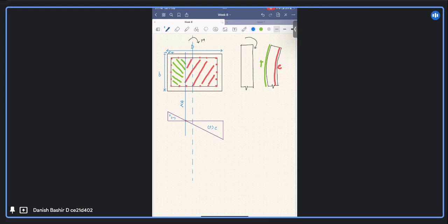So now we have to find the strain at each reinforcement, and then we have to find the total compressive force acting on it, and the total moment coming on it. For that, the code gives the formula like this. This can be easily derived from integration, but we will not go into the detailed calculation. We only require the formulas for solving our analysis problem. So let me draw the stress profile for this as well.